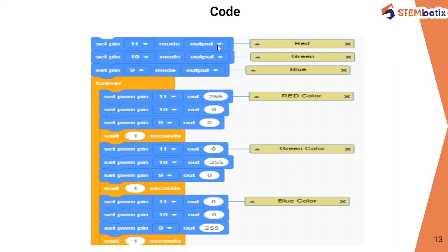Now, because we connect our LEDs to PWM pins, as I mentioned before, PWM is pulse width modulation, and it varies between 0 and 255. So we will get other color combinations. If we need some color combinations, then we can adjust this value accordingly. But in this scenario, we just need red, green, and blue LEDs. So let's take a basic example, and we will operate these colors.